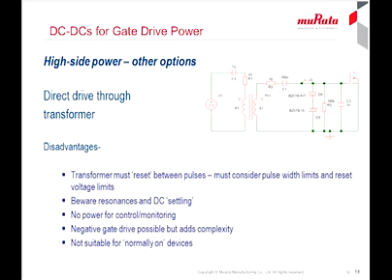High isolation and large size leads to high leakage inductance, which in turn slows down the edge speed of the PWM waveform, risking power loss in the switches. Of course, the PWM source also effectively has to be a power driver supplying the watts of power needed. You cannot just use outputs of logic gates, adding again to cost and complexity.